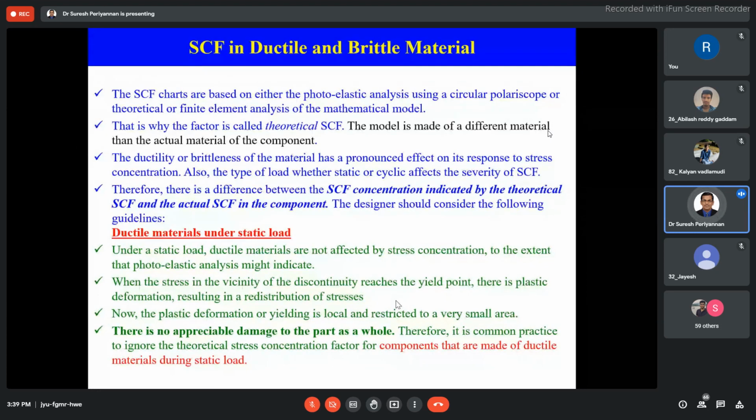Like that we use. Hence, even though we are under the elastic limit only, when there is more stress concentration, it will fail, right? Failure here means plastic deformation, because our designed component is still in the elastic region only, since we are already using some factor of safety. That's what we are saying here.